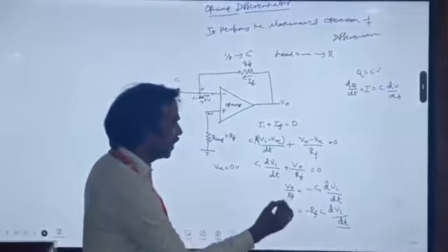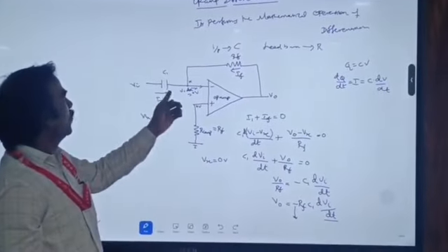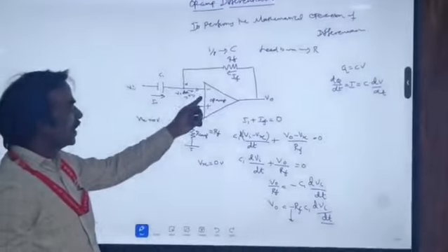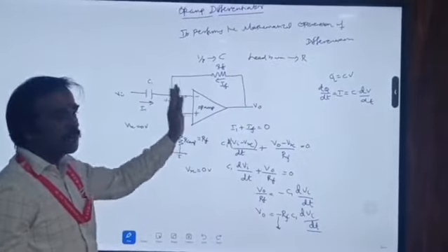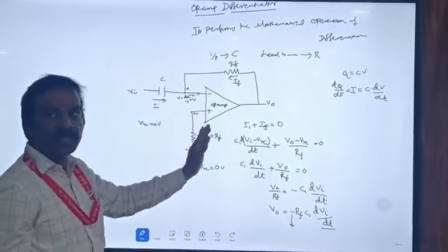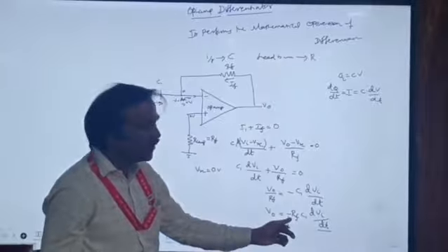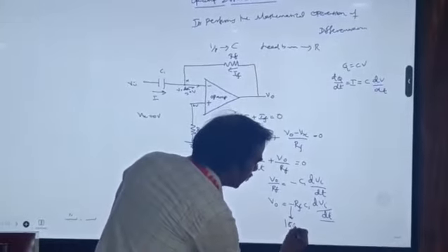This is the output. What is the meaning here? Since we have connected the input voltage to the inverting terminal, it looks similar to the inverting operational amplifier. It is working in the mode of the inverting operational amplifier. So here we are having a 180-degree phase shift.